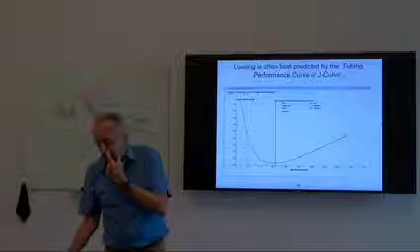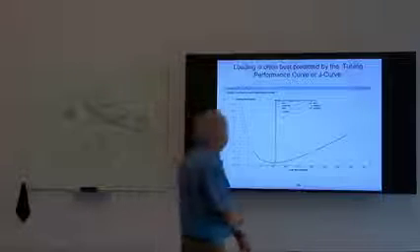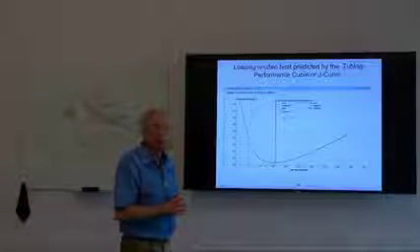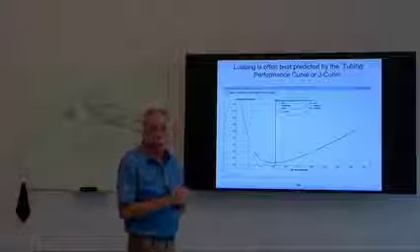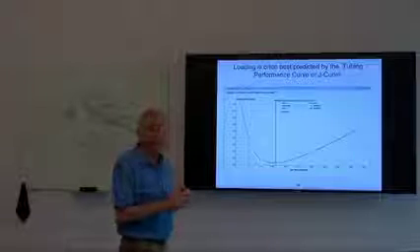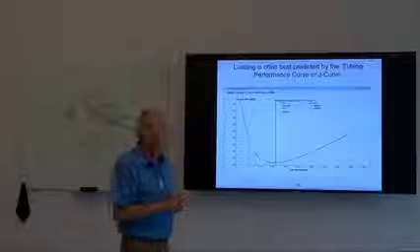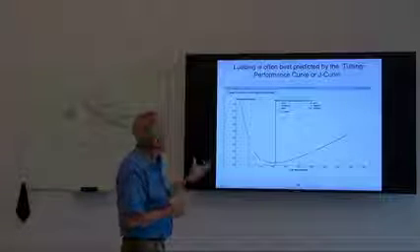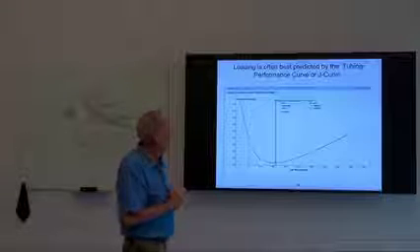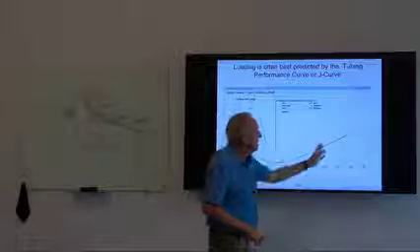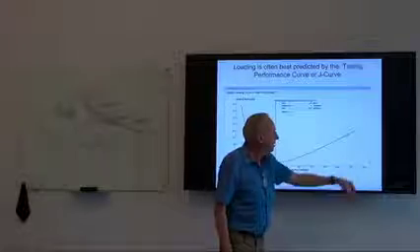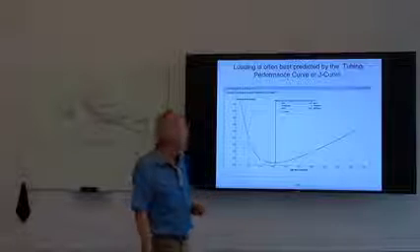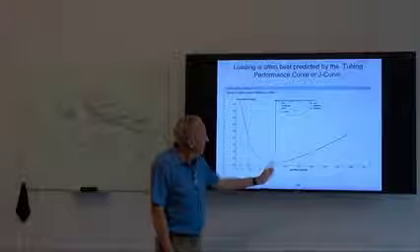If we were to examine this J-curve or tubing performance curve in a different way, this is from a program called PRODOP, which is an older nodal analysis program that was created by Dr. Lee a number of years ago. We were primarily using SNAP as our nodal program these days, but we can generate a J-curve, and here we see the friction side of the curve. I'm just going to call that the friction side of the curve, and this the hydrostatic side of the curve. And somewhere here in the middle,